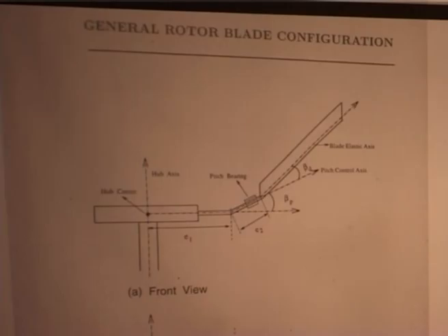and this will have a lot of effect in torsion. So, you see flap, if you look at it, both configurations there will not be major change, lead lag there will be a change, torsion there will be a lot more change, which will go to pitch link load. Then you say which one is better. Okay. This debate goes on because changing a configuration from one to the other is not an easy task in the actual design. Finally, you live with it, whatever load that comes, and you try to minimize something here and there. So, but each has its own plus and minus.